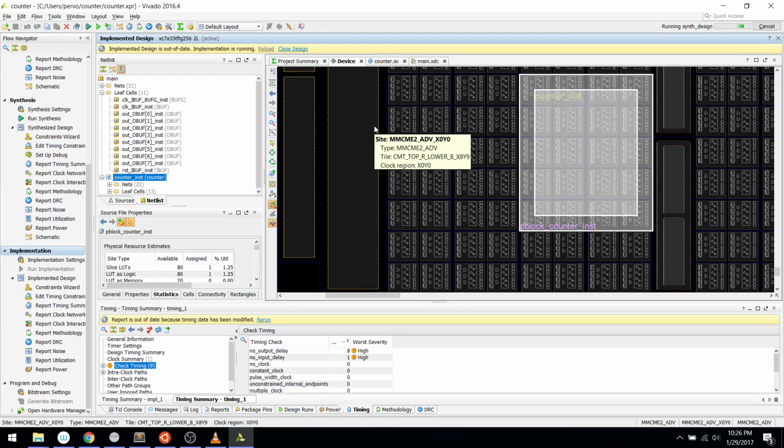This is really useful, although this thing specifically has its limits, but basically you can use this to do absolute placement of big blocks. You typically don't want to use this for super fine-grained submodule placement because one of the issues is that P-blocks are absolutely positioned, and so they're very specific to exactly how you've laid things out.